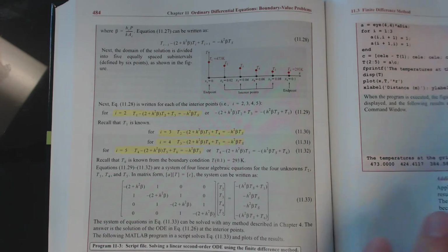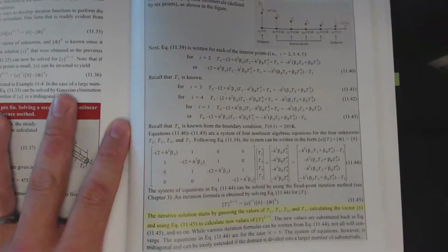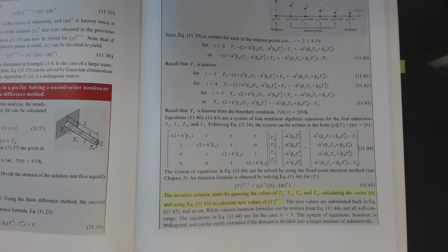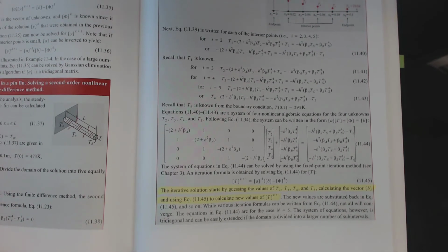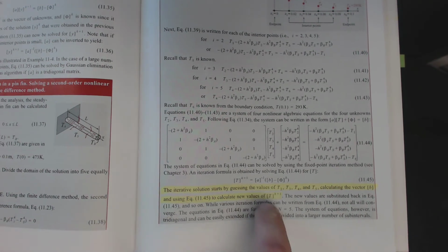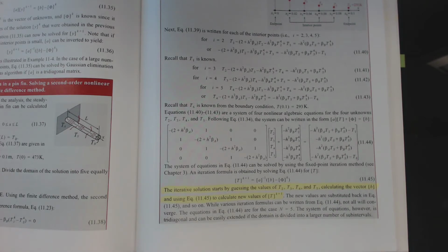If you go beyond the linear region of a material due to excessive strain at any point, even if it's just one point in the entire domain of finite element solution, you'll oftentimes be asked, do you want to employ the nonlinear iterative solution method? And that's exactly why. You've taken the solution methodology away from the quick invert, multiply, or otherwise quick matrix solution methods, and now you've gone to an iterative nonlinear equation where they have to use their nonlinear models for materials in combination with the equations using that same data.